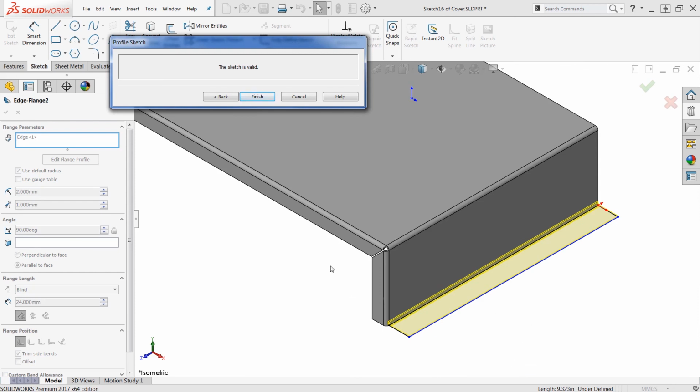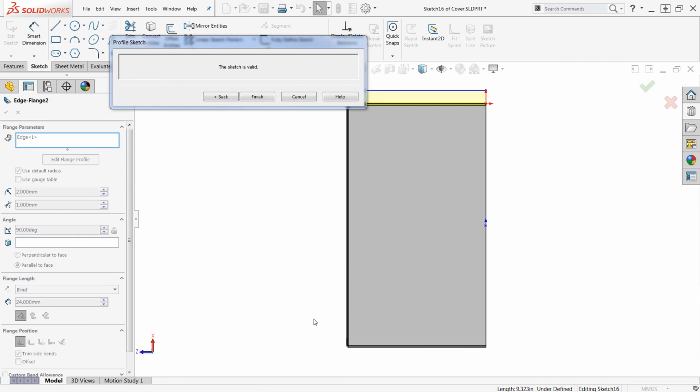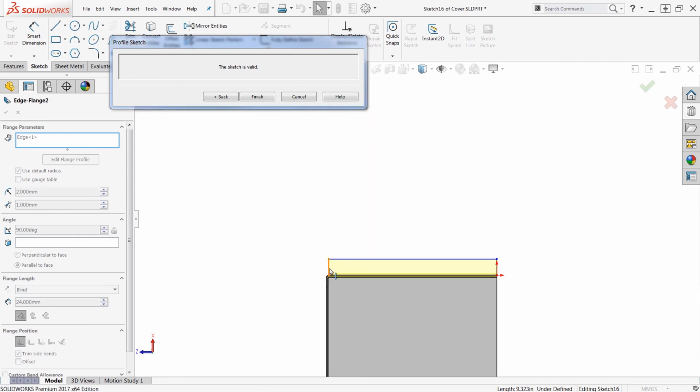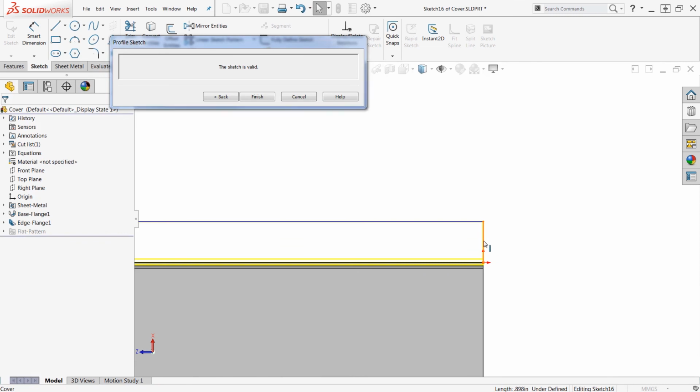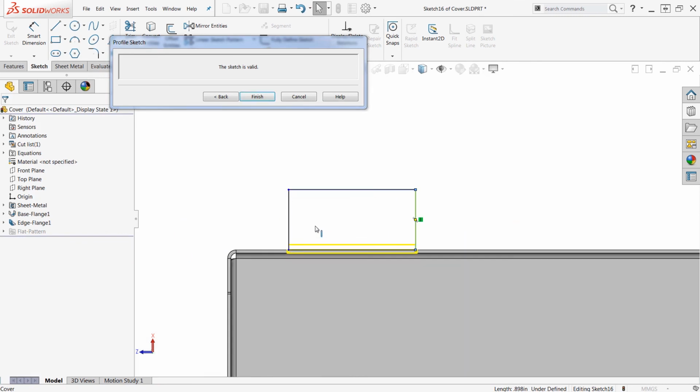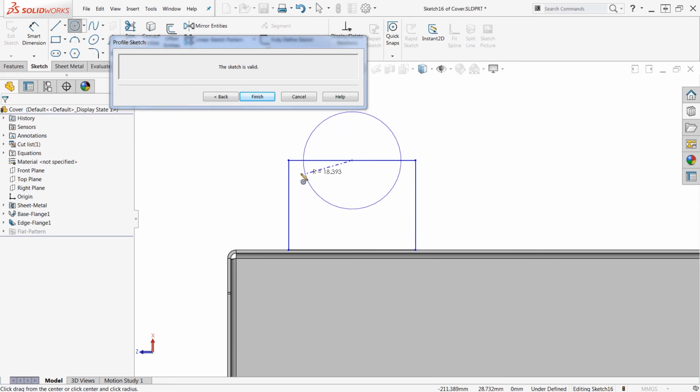All right. And as such, when I activate my mouse gestures, I can see I have my regular sketch tools. I've customized mine so that I have bottom swipe, or the south swipe, as my normal to view. I'm going to swipe for that, normal to. And what I can do is actually push these sketch entities and make a change to that. Push those around like that. Now I can modify this. I'm going to actually pick up a circle. Here's a little trick I like to do. I'm going to turn this so that it has an arch on the front of it.